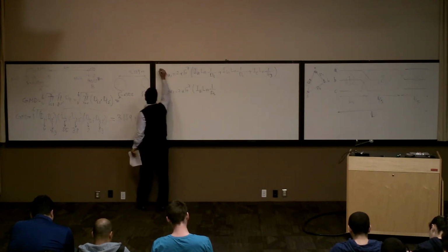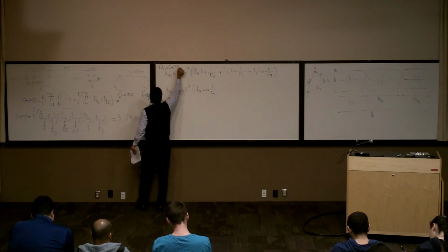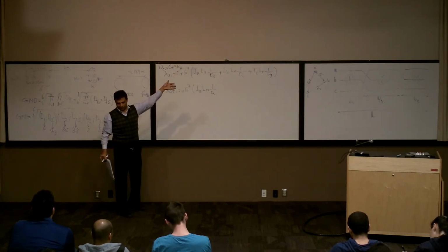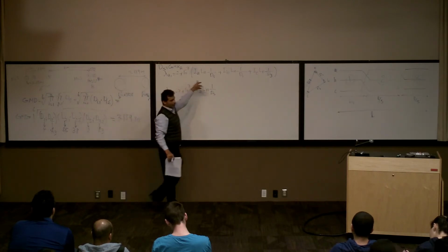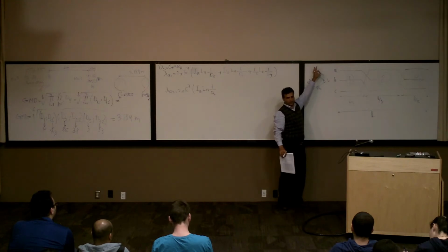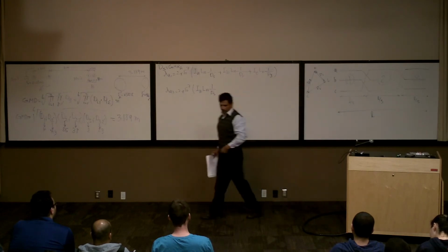DS is the GMR of A or B or C. They are all the same, right? If I put r prime on, it means this is a single conductor. It doesn't have to be a single conductor. It could be many conductors, right? Instead of r prime, you put DS or GMR. You can replace it with GMR.